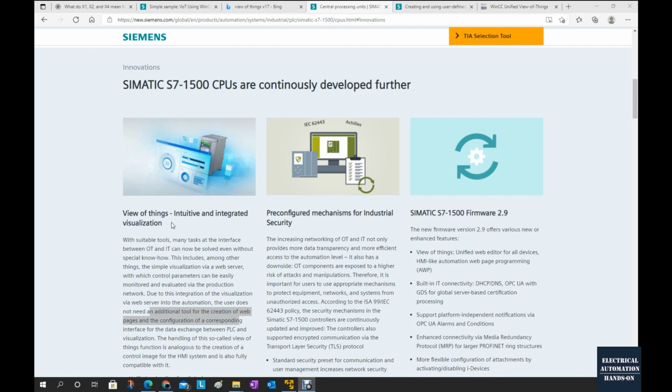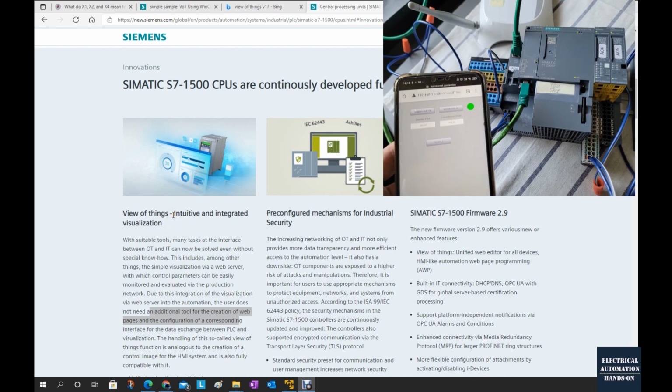Since this is a built-in function from the S7-1500 PLC, it is not widely known. However, from my personal view, this Web of Things is very helpful, for two points. Firstly, it can facilitate us during commissioning, especially before we deploy the official HMI. As we know, in some cases, for example motion control, we need to power on, forward, reverse, and monitor the speed and the velocity.